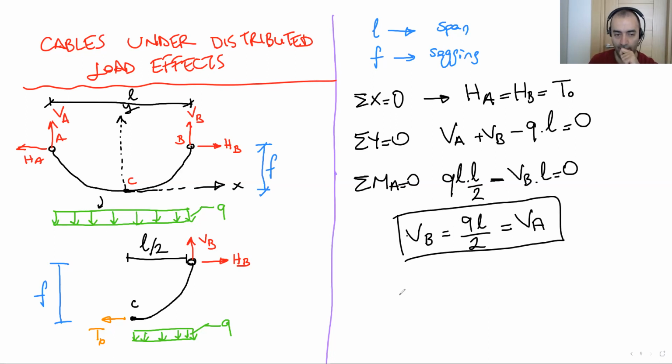And we cut the system from point C here, as you can see. Let's write the total MC. I'm going to take moments around point C. HB is a lateral load, but it has a vertical distance, which is F. So I have to consider it.